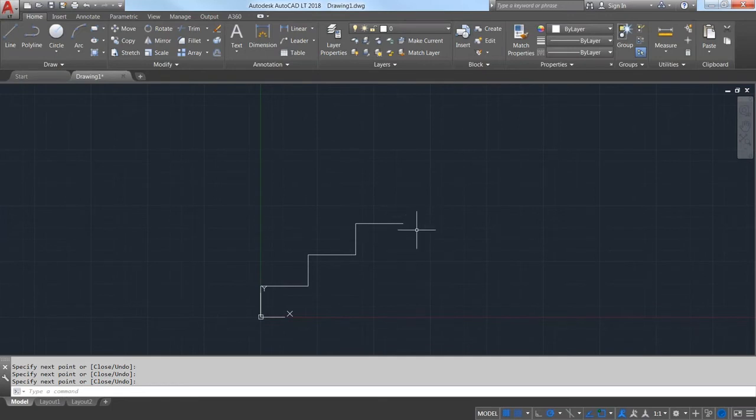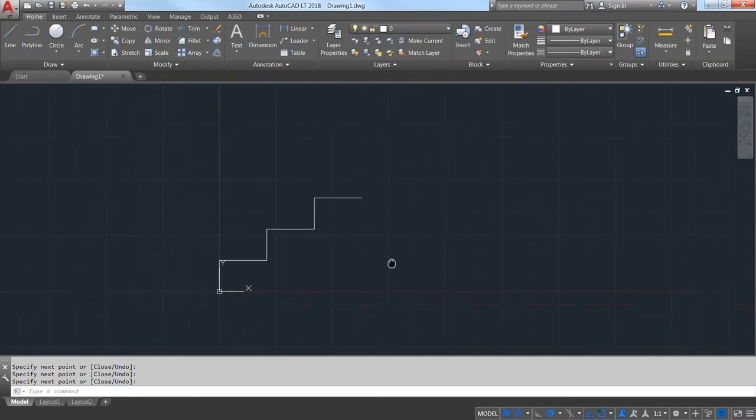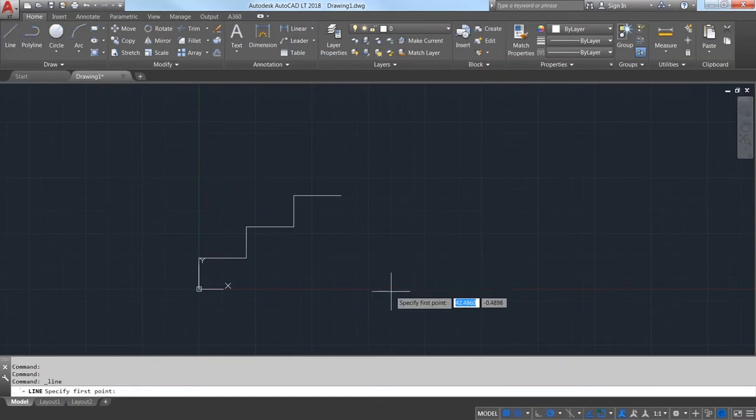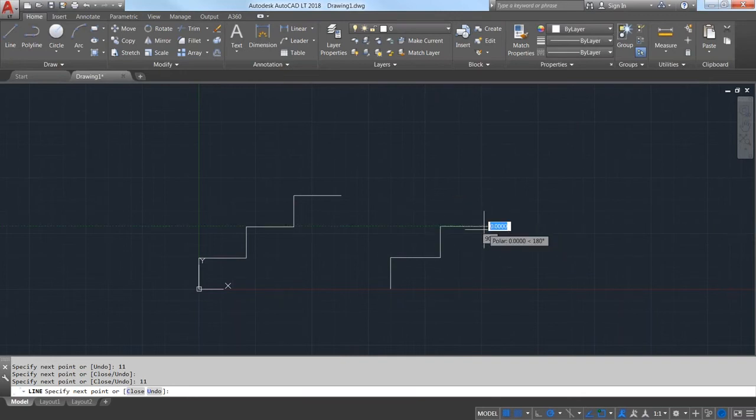And if you found that you ended up wanting to go 7 up, 11 across, like it's supposed to be, the actual 7-11 standard, we can do that too. We can go up 7, and even though we've got the snapping turned on, we can just point our cursor in this direction along the snapping vector angle of 0 degrees and just type in 11. And then we can go up 7, click, go over, type in 11. And go up 7, and now we don't want to go 14, we want to go 11, so we'll type it in. There we are. And we'll just press enter to get out of it.